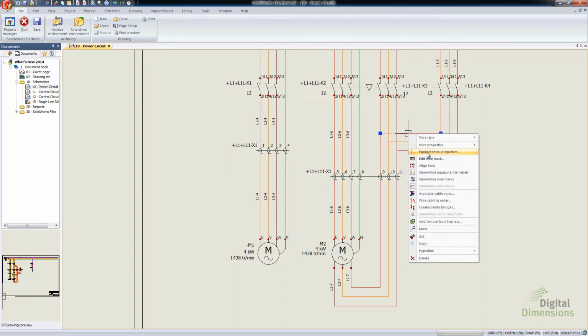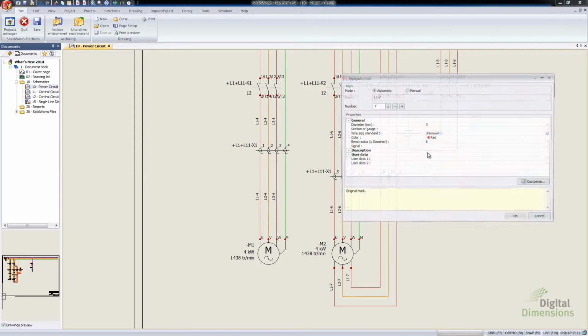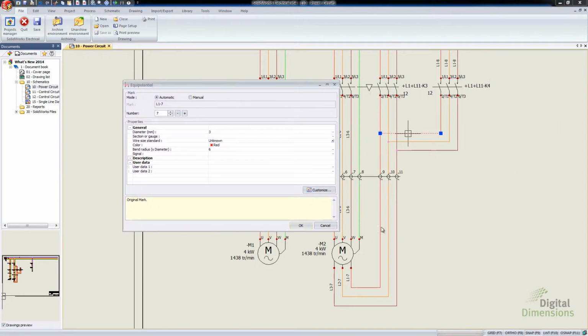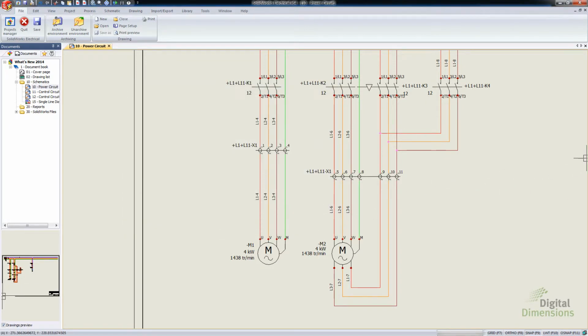So rather than just doing one wire segment, the Equipotential, let me move this off to the side here, will actually get me that segment and the jog over here. So all of these at the same level. Now I'm actually controlling the settings within there. And again, makes it a lot easier to manage all your wire and properties all in one shot.